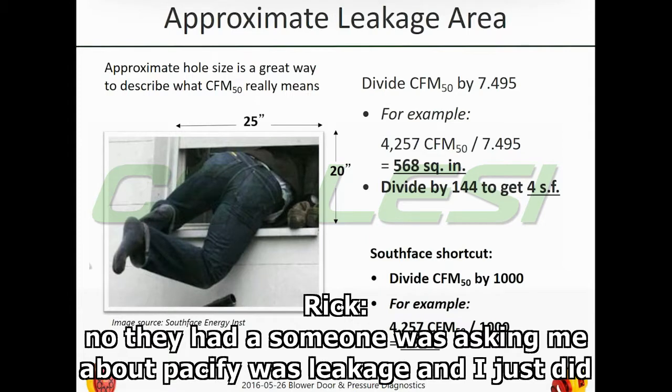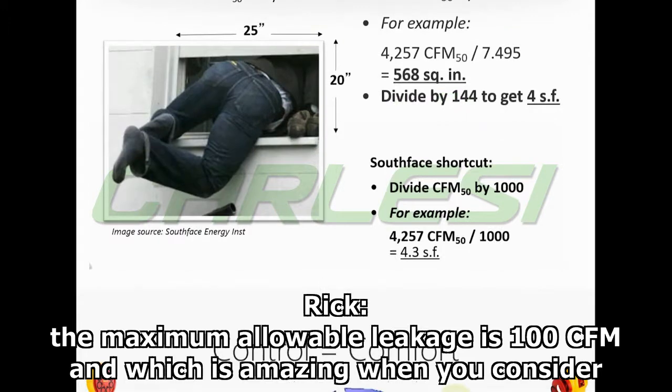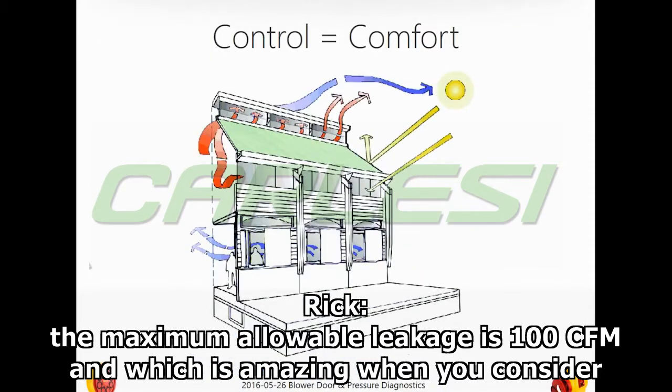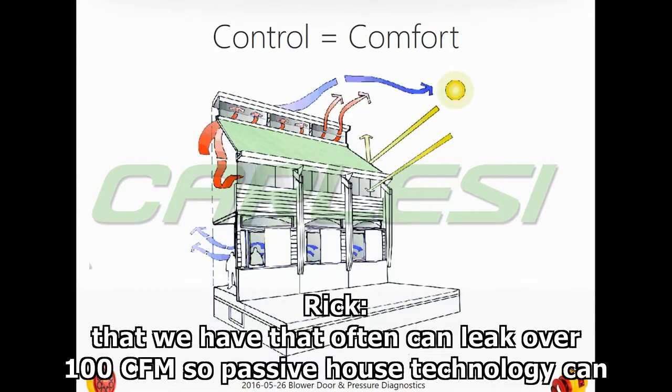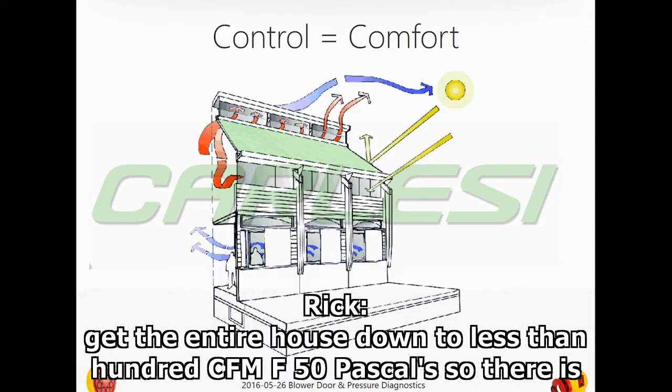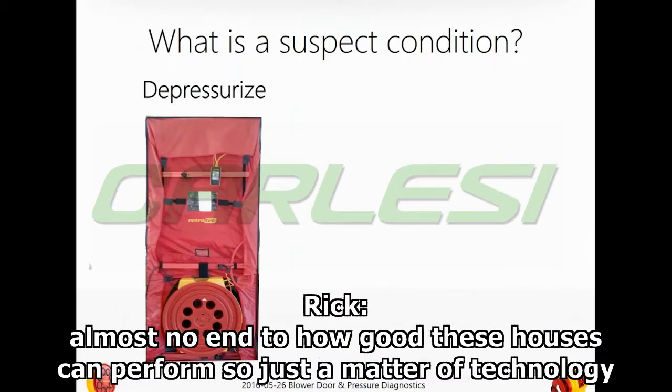Someone was asking me about passive house leakage, and I just did a calculation for a 10,000 cubic foot house, so it'd be like 1,200 square feet. The maximum allowable leakage is 100 CFM, which is amazing when you consider that passive house requires the entire house to leak less than the duct systems that we have, which can often leak over 100 CFM. So passive house technology can get the entire house down to less than 100 CFM at 50 pascals. There is almost no end to how good these houses can perform. It's just a matter of technology.